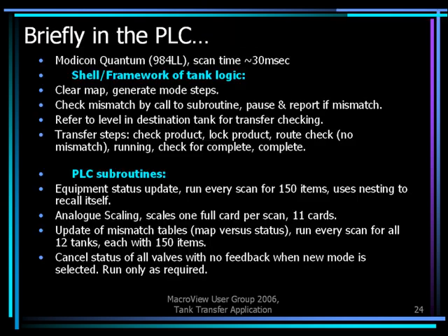Are these fundamentally important valves, or are they like overflow valves? You know what I'm saying? I mean, Brad, you don't want to go there. Some of them are important. You'll have situations like if the operator just decides to confirm valves that are not really in the right position, you'll have no flow switches and overpressure type detection elsewhere within the system that will make sure that you're not doing anything too far wrong.